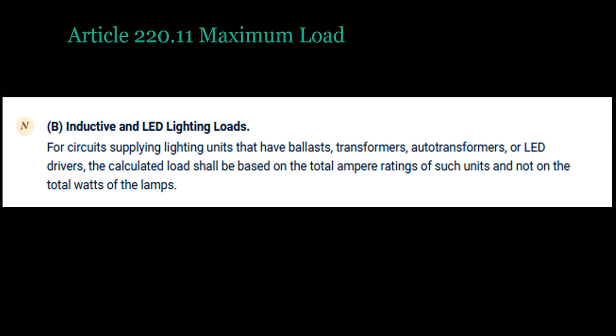Inductive and LED lighting loads. For circuits supplying lighting units that have ballasts, transformers, autotransformers, or LED drivers, the calculated load shall be based on the total ampere ratings of such units and not on the total watts of the lamps. The classic statement in teaching is that when you're calculating loads, for example, fluorescent fixtures have ballasts in them, of course. When you're calculating the load for a room full of fluorescent fixtures, you calculate that based on the ampacity given on the nameplate of the ballast, not by the wattage of the bulbs.